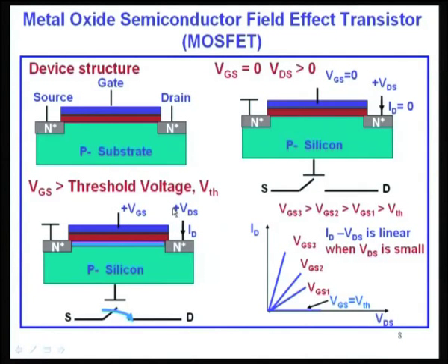This depends upon various parameters like the oxide thickness and the substrate characteristics. Okay. Thicker the oxide, more voltage you must apply to induce the required charge. So, what we are trying to say is a minimum voltage is required, which you call threshold voltage, to create these charges.